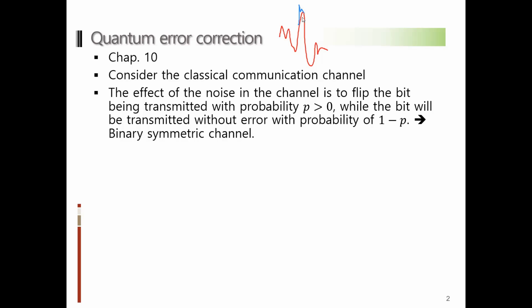Well, in the analog domain, there is still some technology like frequency filtering, because in many cases the noise occurs at high frequency. So by filtering out the high frequency component, maybe you can regenerate the original signal very closely, but